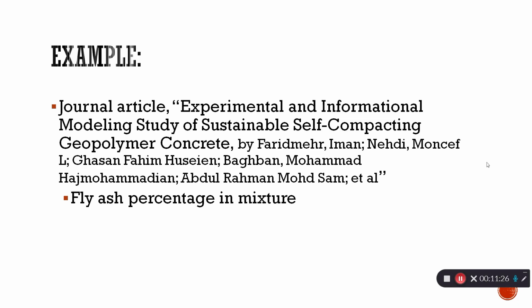When the fly ash replacement levels for GBFS were 40, 50, and 60%, the flowability, resistance to segregation, ability of filling, and passing capacity were on par with the standard requirements for fresh concrete characteristics. The plastic viscosities of these mixtures reduced between 0 to 50%, but increased when fly ash was at 60 to 70%. The chemical compositions and the changes in the physical properties of these mixtures would be why there was an increase in plastic viscosities when fly ash was increased in the mixture.